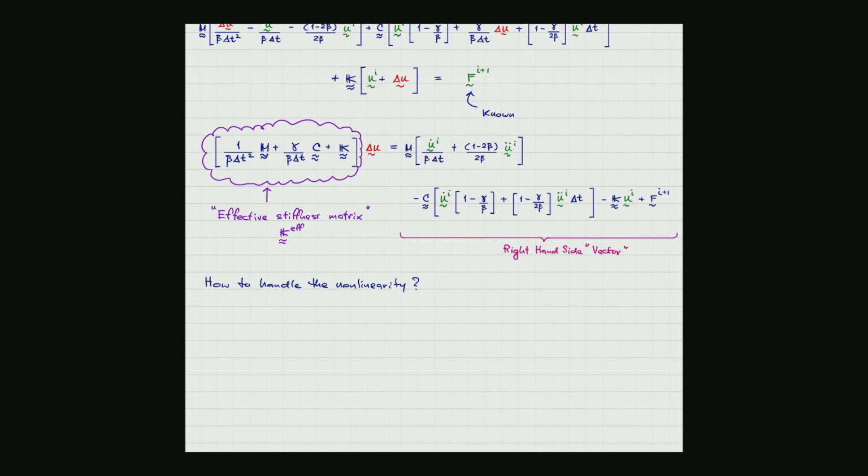It is going to be very fast when you run the linear analysis, if you can control your code so that it reuses this number and doesn't recalculate the stiffness every time. The recalculation of stiffness is not bad, but inverting the matrix is the bad part.